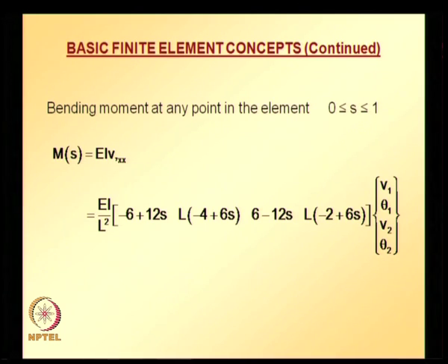As I mentioned earlier, the 2 node beam element that we developed gives us an accurate prediction of bending moment if the bending moment in that particular beam problem is linear with respect to the spatial coordinate.